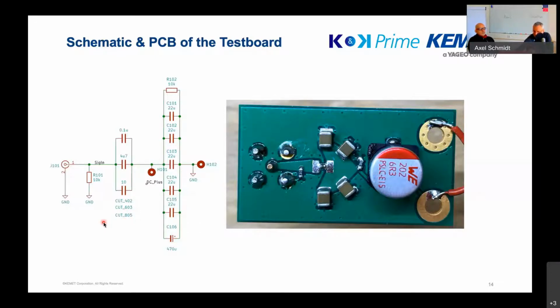All that is possible. The same as you have seen on the picture before, the connection from the base side from the capacitor on the test to these capacitors needs to be close and robust, to give this capacitor a good ground, or a good AC ground, while we charge it through the DC side with some DC bias. They are also spaced in equal length so that they don't get any kind of parasitic resonance.